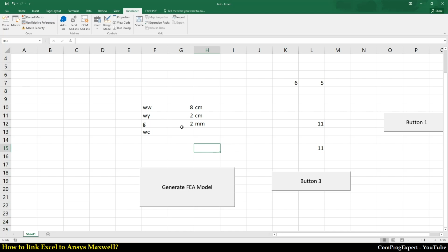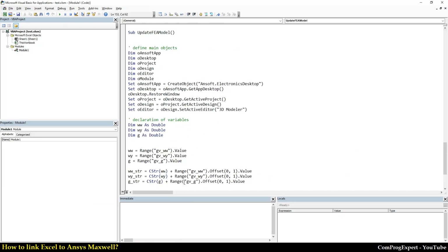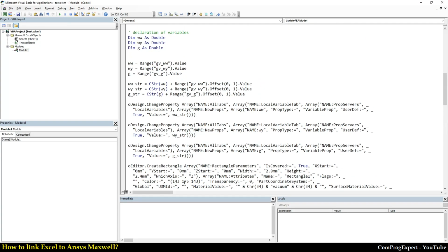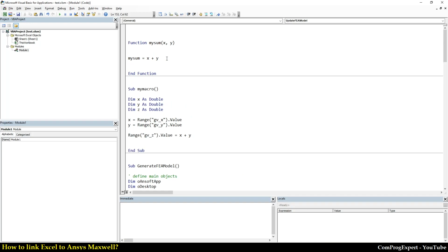I don't think to explain and extend the time of this video. So this is what you need to call the ANSYS Maxwell from Excel, generate a new finite element model, update the variables. You can run simulations and return results, implement your optimization methods in Excel, and store the data.